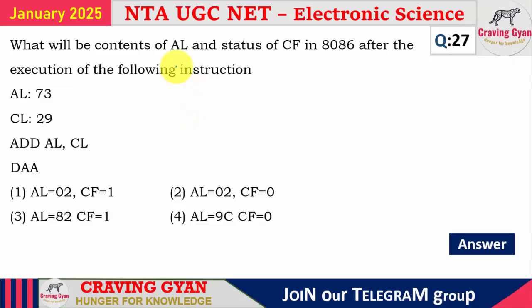In the 27th question, they ask what are the contents of accumulator AL and the status of the carry flag in the case of the 8086 microprocessor. They have given some instructions. The value of AL is 73 and the value of CL is 29. They are performing addition of 73 plus 29, and the result will be stored in the accumulator AL register. After addition, they are executing decimal adjust after addition, the instruction DAA.